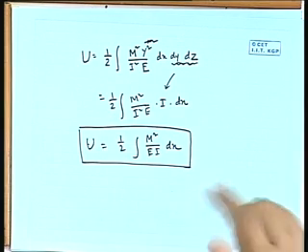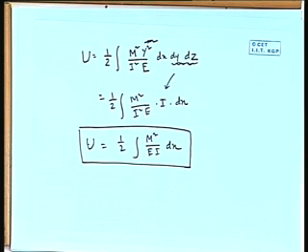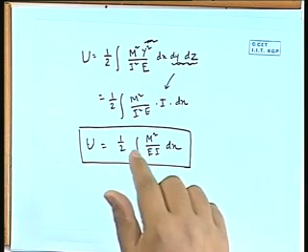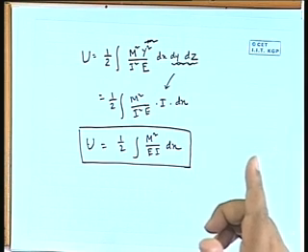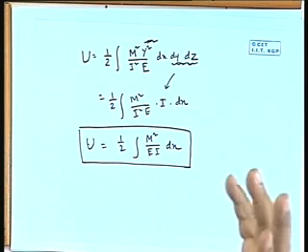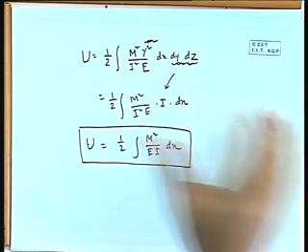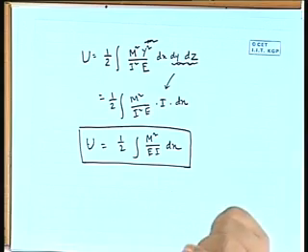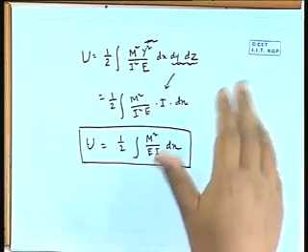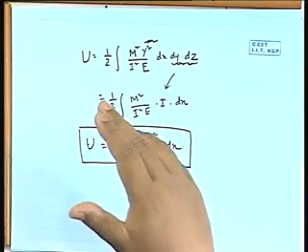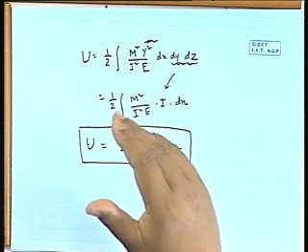Epsilon we have expressed in the form of sigma by E, and the sigma we have written My by I. So, this y square dy dz, that part is simply I. So, ultimately it will lead to integral half M square by EI dx, it will be the energy, right. Now, for bending mode, whatever bending moment is there, square of that divided by EI into dx, half, that will be the U.